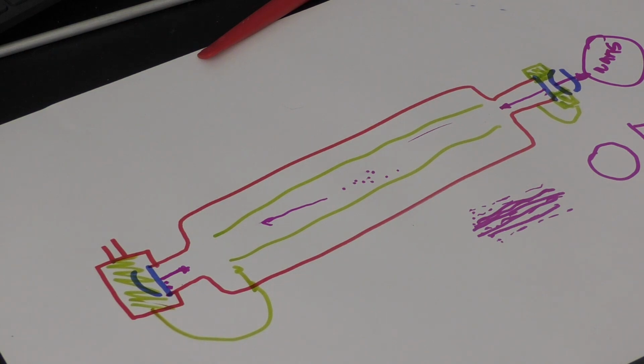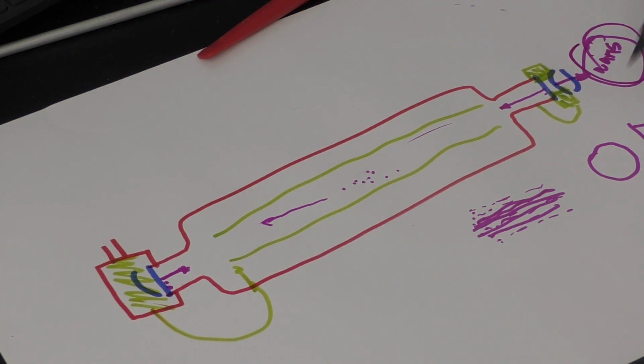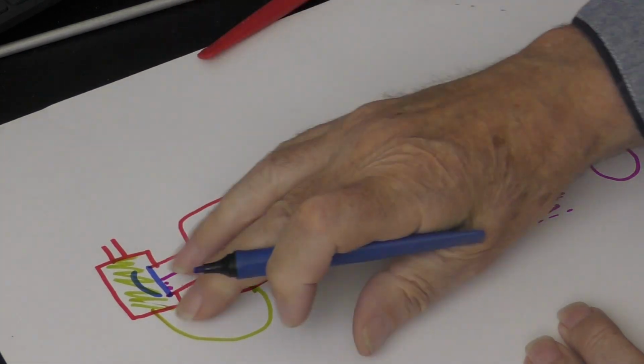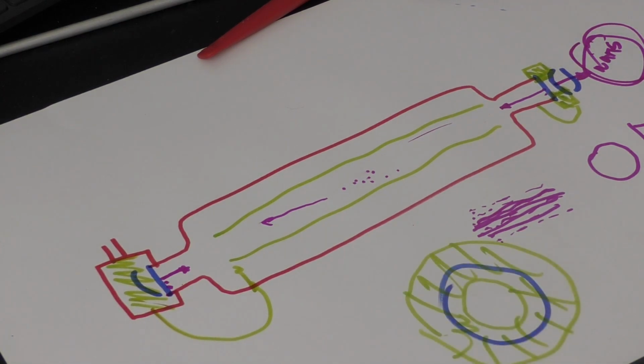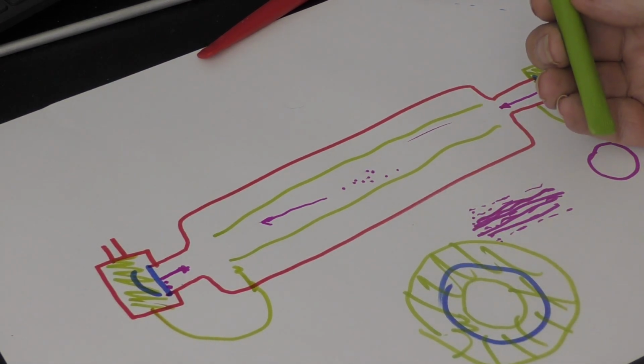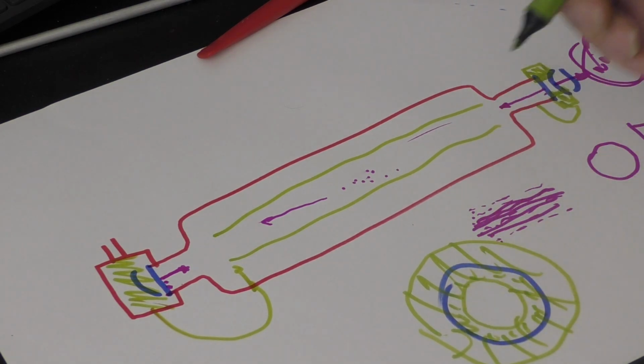That's an interesting point, isn't it? We've got a conflicting requirement here. We need the mirror to be cool, but we can't have this mirror completely covered with water. We need an open space through the middle of it to get our watts out of. This mirror here is being 100% cooled across the whole of its flat surface, but this mirror here, it's only receiving cooling round a little annulus round the outside. So we've got a very flat glass mirror which has got cooling in an annular ring round the outside.